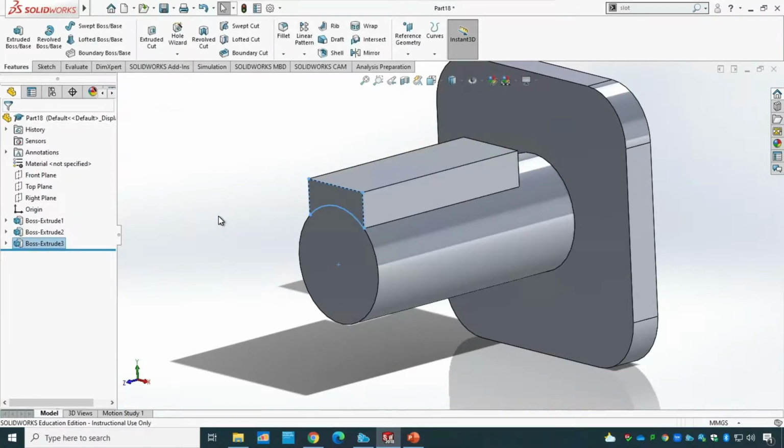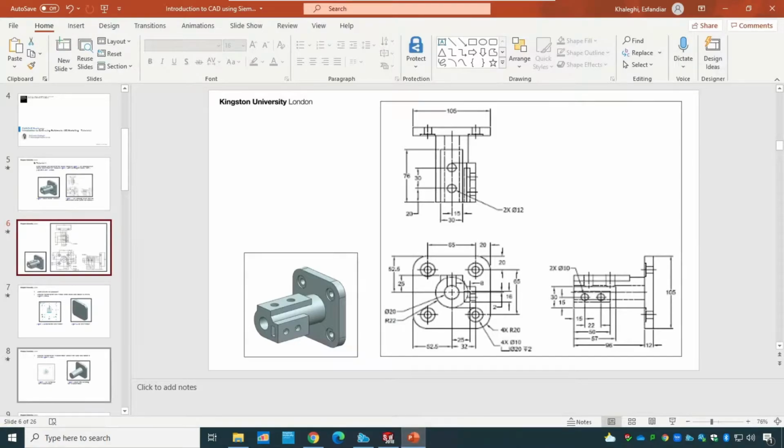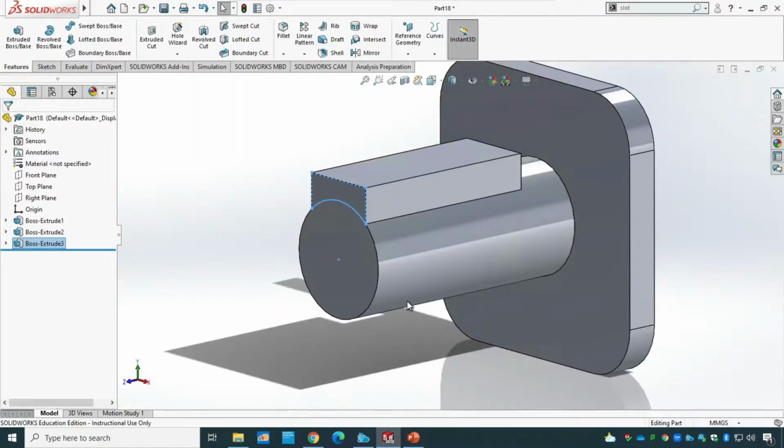So you can see this is what we've done on that part, and we're gonna go and apply this part as well. The information I have on the side is 32 here. As you can see, that one is 32, and I do have a side of it that is 30, so I get it from the side view in here. So it's a 32 by 30, and then we will have a curve in here, and also I need to extrude it by 57 basically from that view. So it's quite straightforward, like what we've done in here.